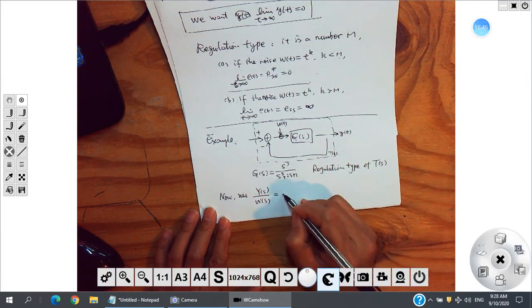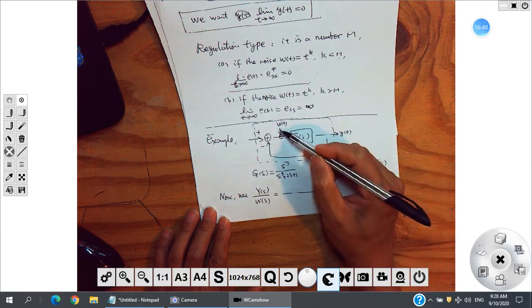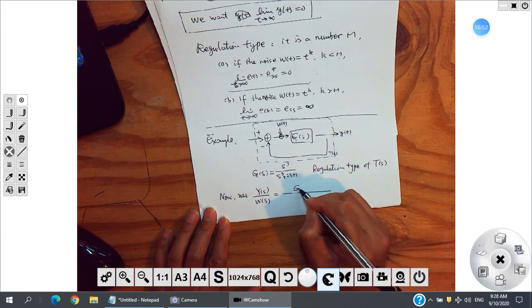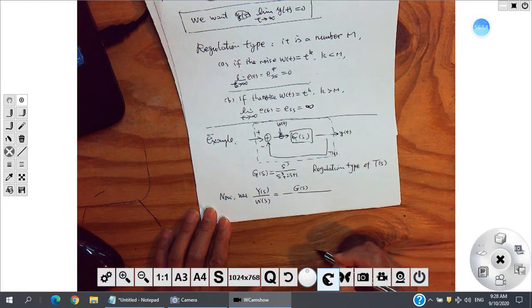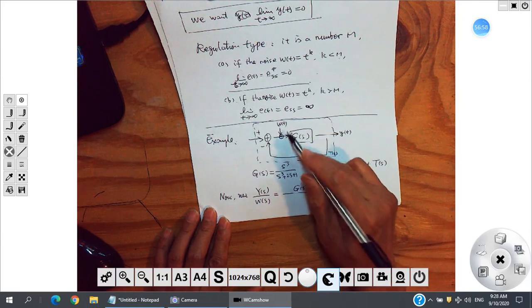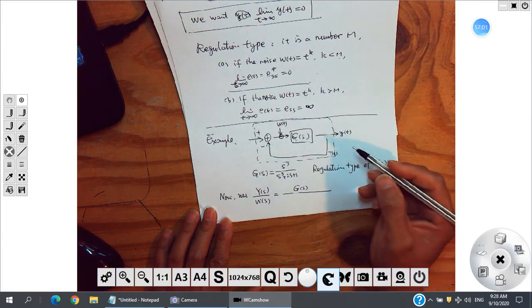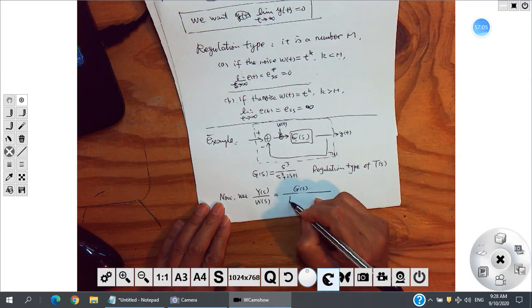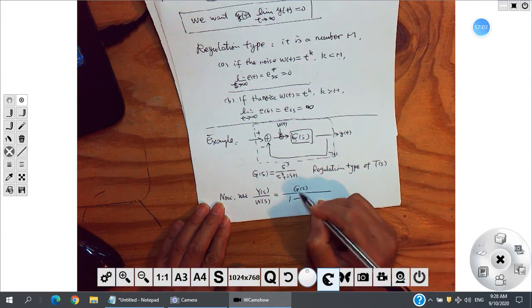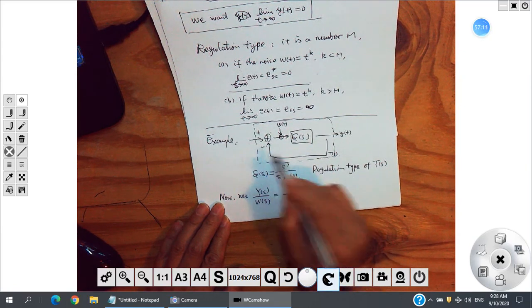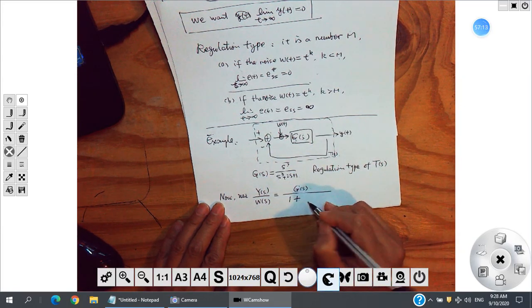We use this one. This one equals what? We still use the gain formula. We have one forward path with gain just G, right? And the numerator factor should be 1, right? Only one loop, and the loop touches the path, so we do not use any loop in the numerator. And the denominator is 1 minus that loop. That loop is G, and here is a negative, so minus negative G, the plus G. Okay, so this one.